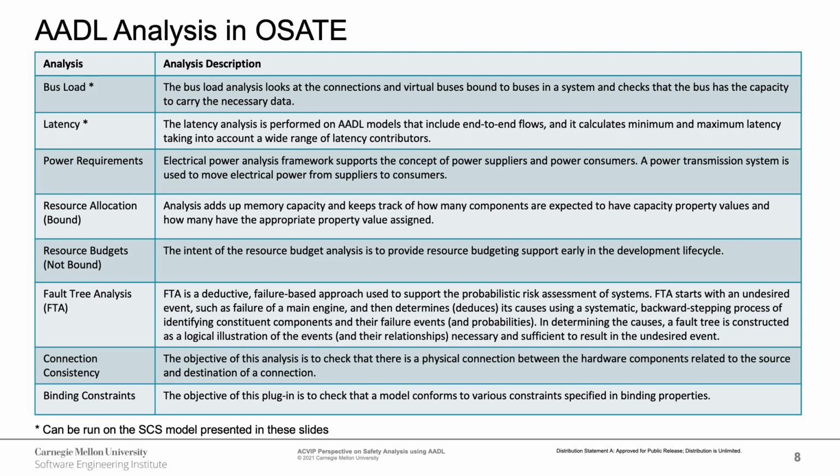Other methods include failure modes and effects analysis, FMEA, and its variant failure modes, effects and criticality analysis, fault tree analysis, FTA, availability and reliability prediction via reliability block diagrams and stochastic Petri-net or Markov models, and architectural designs such as using system partitioning as a protection scheme for fault isolation and containment, DO-178B and C, and ARINC 653.